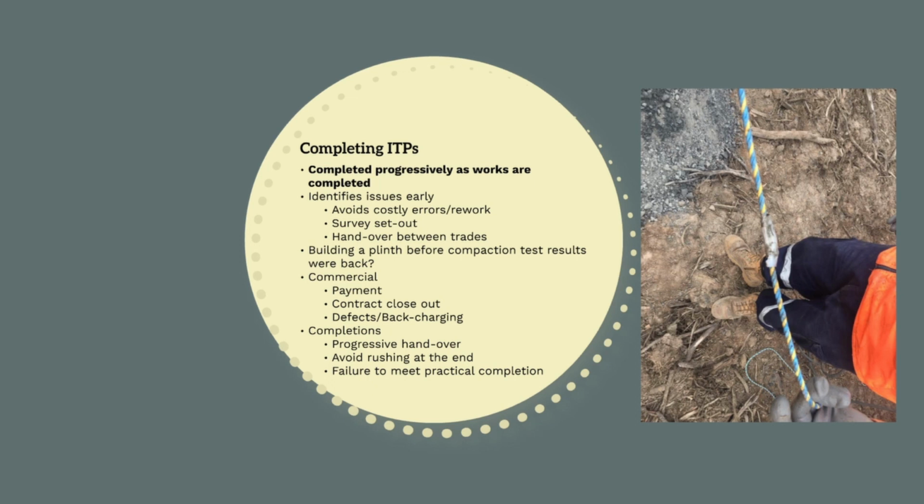The photo on the right-hand side is from a rail project I worked on. It shows a draw rope that had been installed in a conduit and not spliced together correctly. When the cable haulers were pulling cables, the poorly joined ropes kept breaking, resulting in the cable haulers having to re-rope all the conduits, causing us delays and variations from subcontractors.